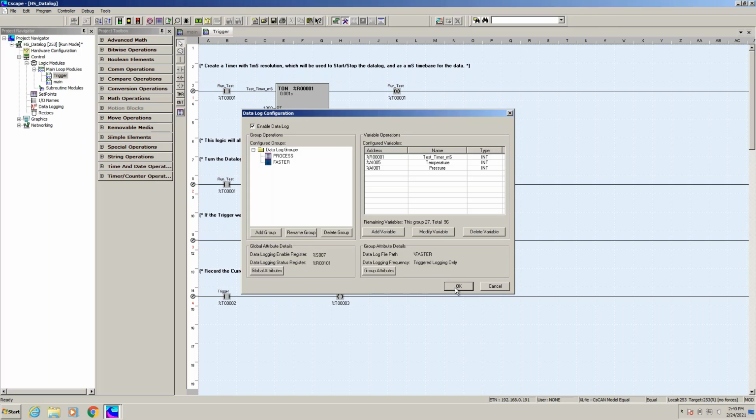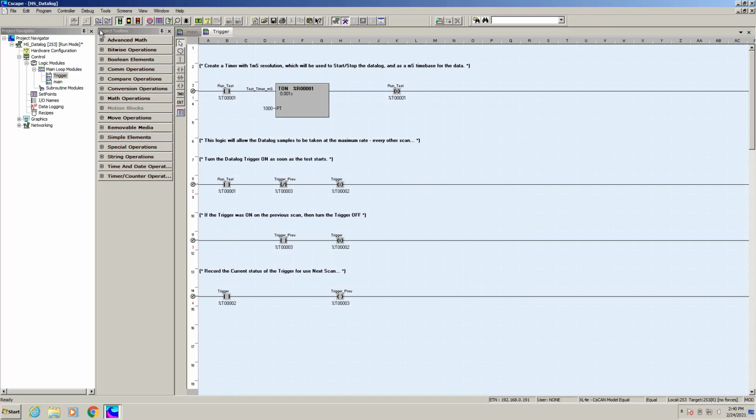Okay, so there's the new data logging configuration. Let me go ahead and download that. And again, this is going to allow us to ultimately log as fast as possible using the standard data logging feature. Okay, so we're downloading that to our XL4. Now, from the standpoint of the new data log group that we just created, it's not actually data logging yet because that's done on demand whenever this T1 test is initiated, that bit is started here, okay?